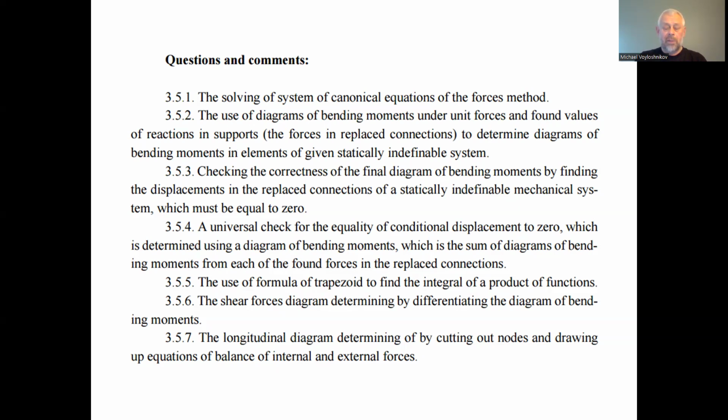To find it, we sometimes can use the Vereshchagin rule, as we did in the previous article, 3.4. But if in the integrand we have a product of 2 linear functions, we have the trapezoid formula to find the integral of the product of 2 linear functions. So we can use it.